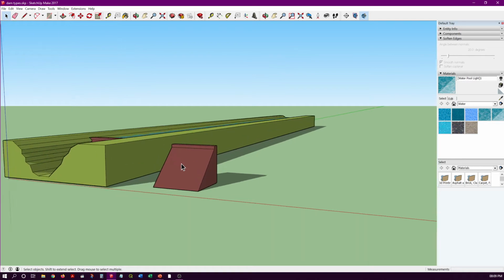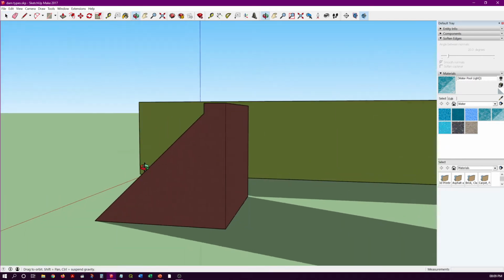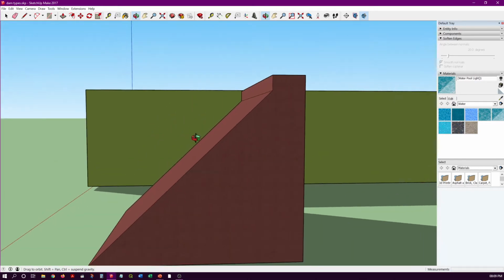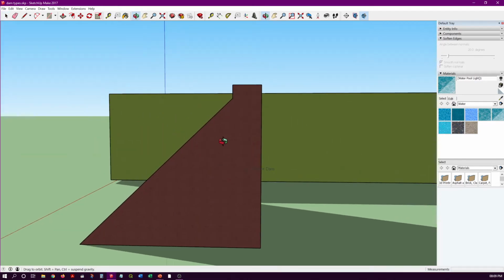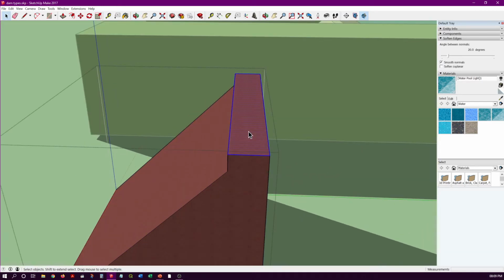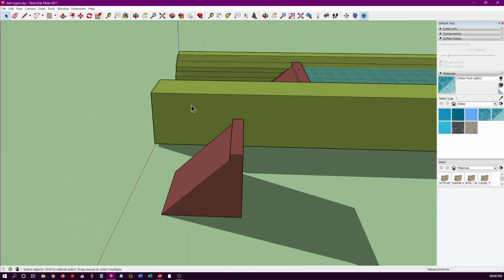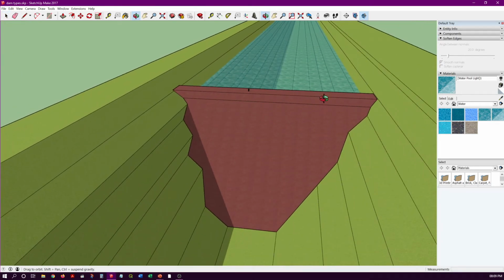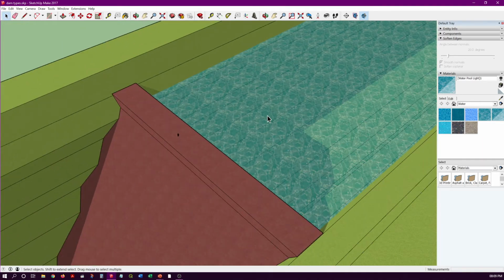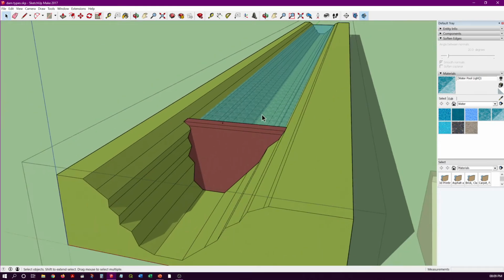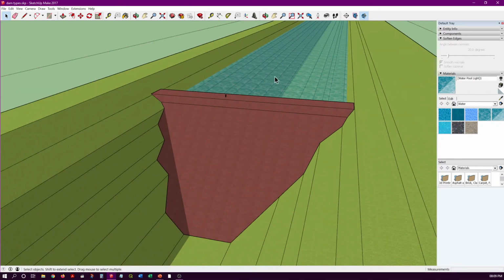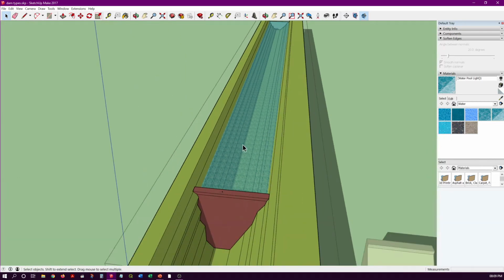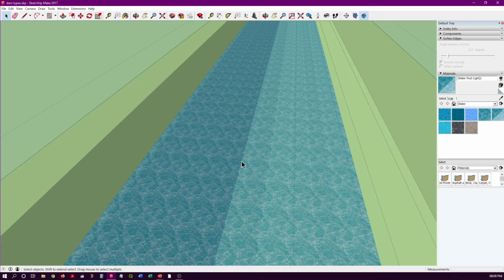First let's look at a gravity dam. A gravity dam looks something like this. It's generally made of masonry or concrete, and the basic profile of this dam is like a right angle triangle with some top width provided for transportation purposes. When we construct it across a river, it would look something like this. Behind the dam we are storing water, because earlier the water depth was much lower. Just because of the construction of the dam, water is being stored upstream, and we have created this kind of a large reservoir. This blue transparent surface is representative of the water.